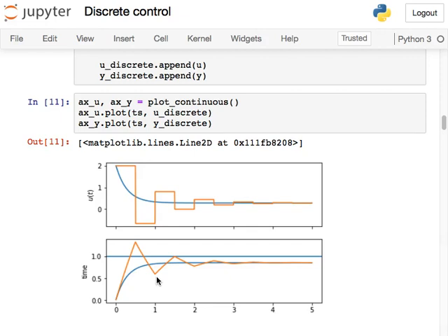Remember, the goal is actually the other way. It's not to try and approximate continuous controllers as well as possible, but to explore the limits of how large I can make the step size and still get acceptable behavior. That's where the interesting part of the analysis is. We've spent a lot of time approximating continuous processes really well by using Euler integration with small step sizes.